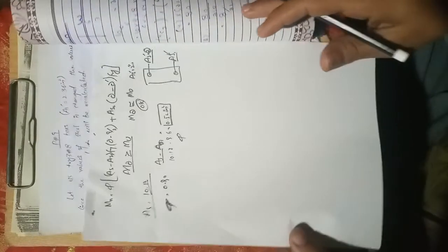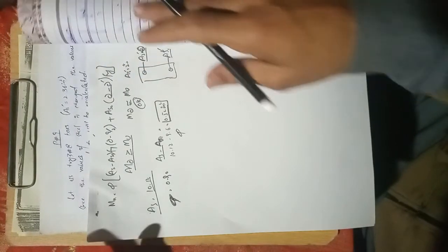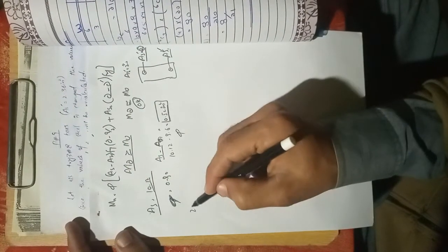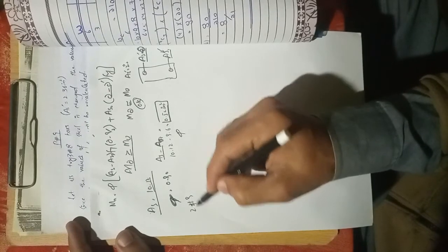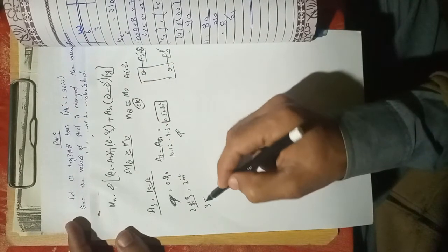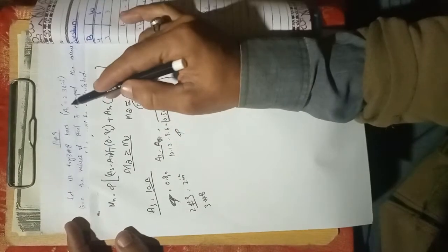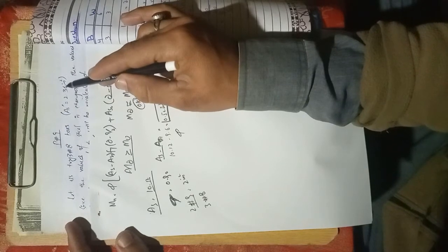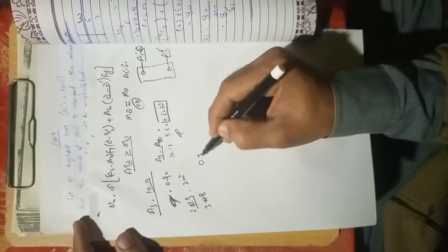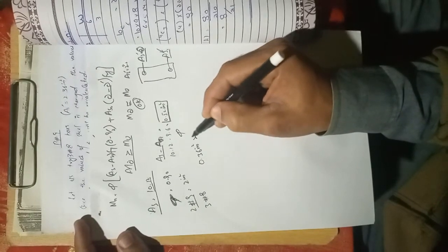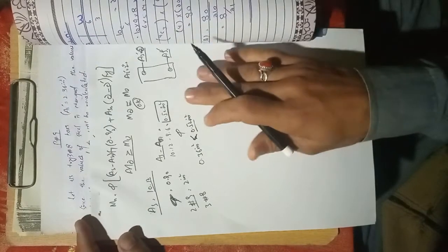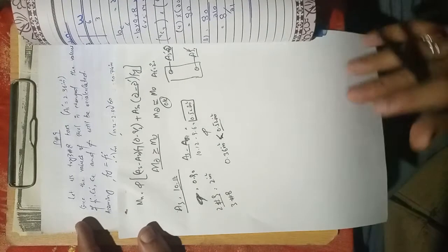So let's say they choose a bar selection. In the initial stage they used two number 9 bars, which give exactly 2 square inches, but this time they are choosing three number 8 bars, which give a value of 2.36 square inches. Now 2.36 means we are just increasing by 0.36 square inches, which is less than 0.52 square inches. So let's see whether it works or not.